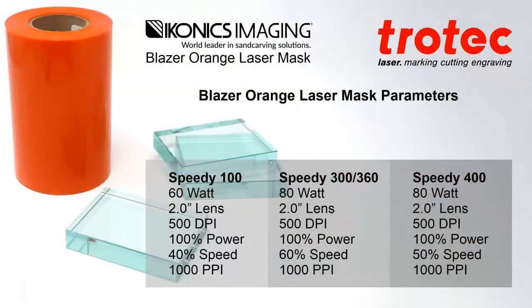Here are those settings again, so that you can take a closer look. I've also posted them in many locations, or you can come back to this webinar at any time and review them. If your system's a little bit up and down, depending on your lens and stuff like that, ultimately it comes down to you want to get through that mask. If you overpower it a little bit and go into the glass a little bit, it pretty much hurts nothing. You're just starting the process for the sand carver anyway. So use these settings, modify or make your own settings, but at least this will give you a good starting point.